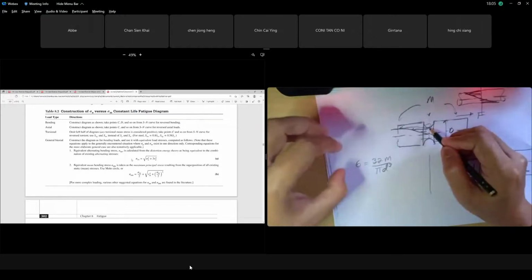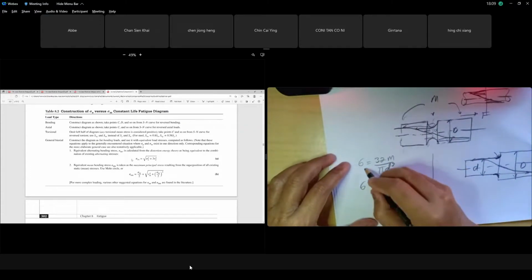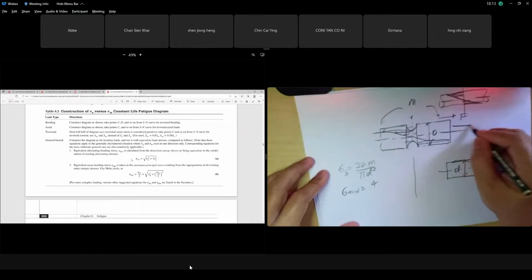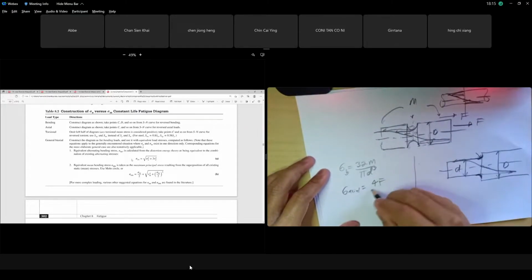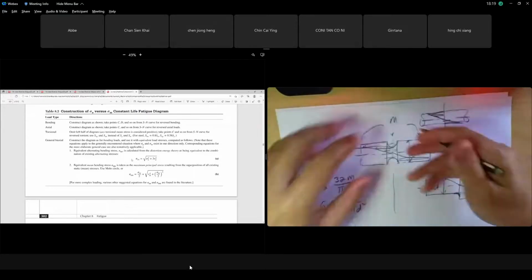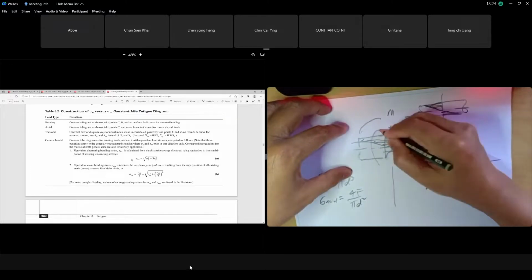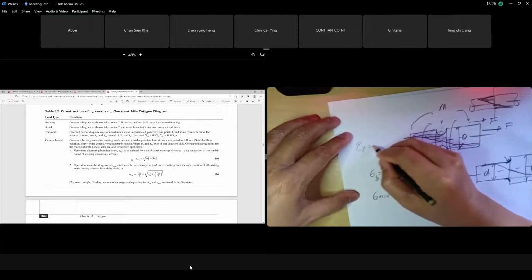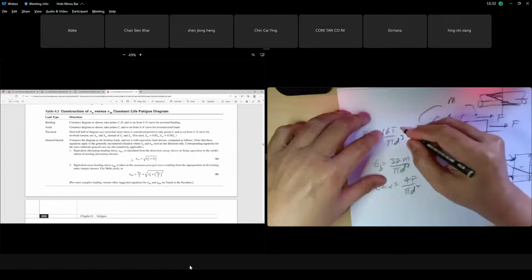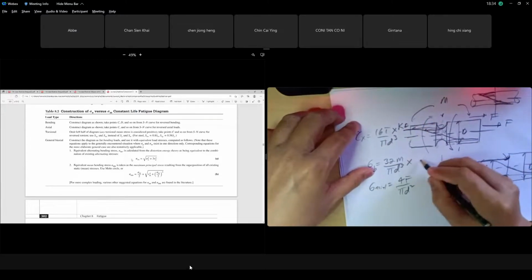But because we have a stress concentration factor, all of our stresses, even our axial stress, this is bending. Axial stress is 4F over pi d square, if we have an external force here. And also torsional stress. Sometimes we have torsion, like this, like that. Our torsional stress is 16T over pi d cube. So all of these have to be multiplied by Kf.